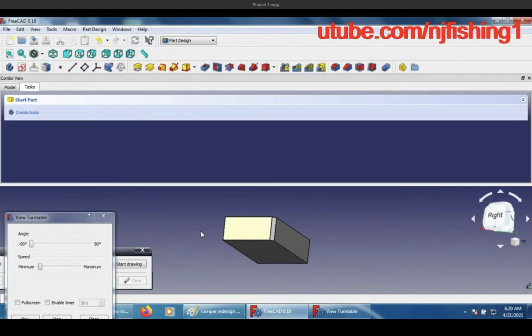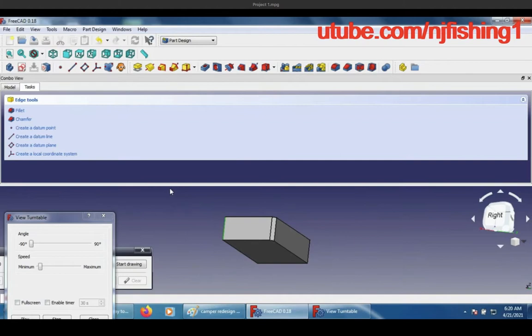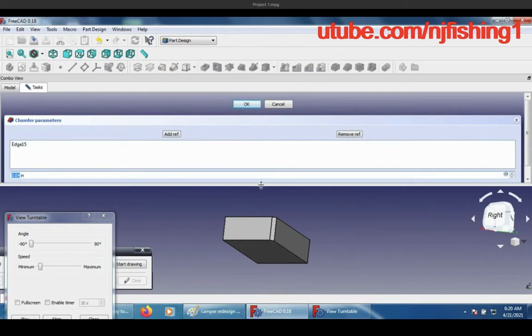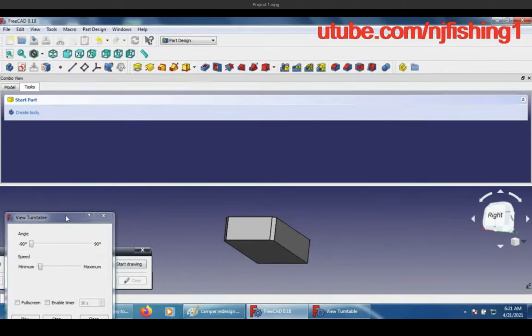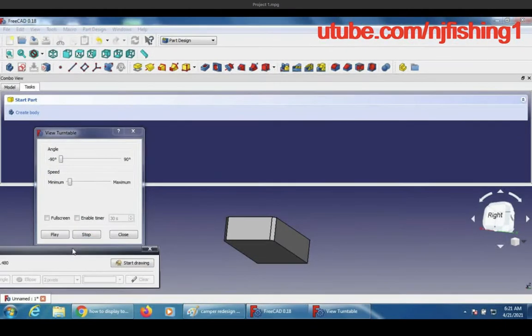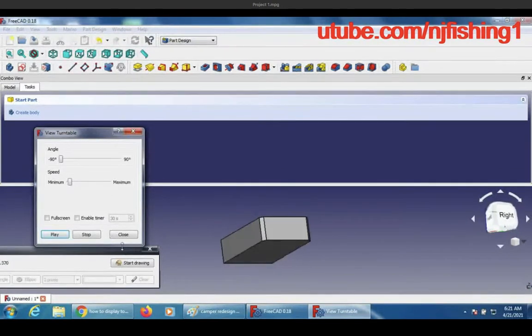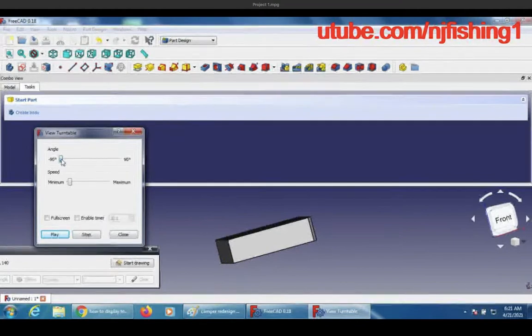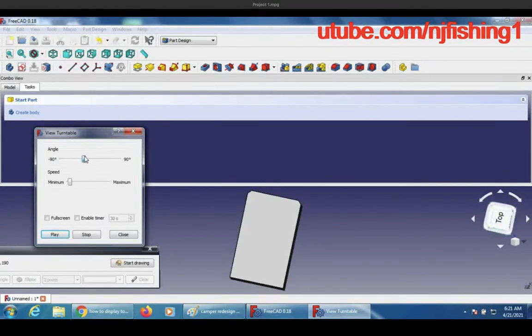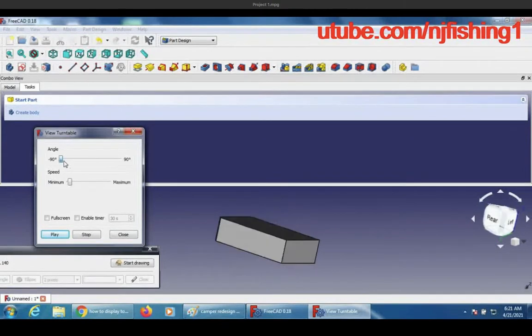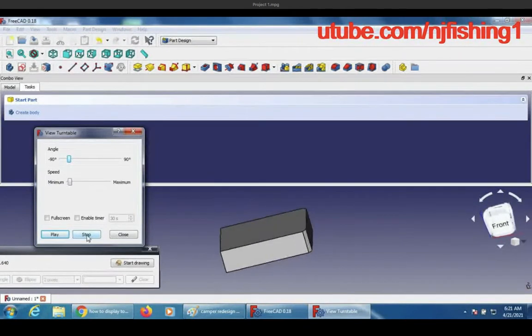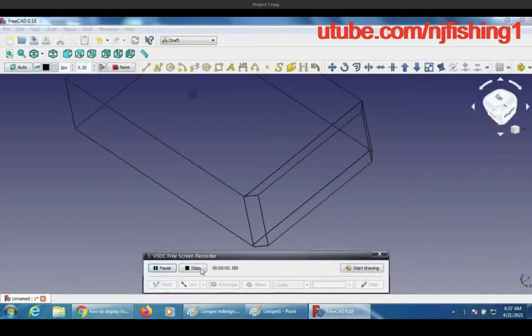First I did 5 inches, and I see it's pretty small, so I'm going to change it. And now here I'm doing another chamfer on the other side. Instead of 0.04 inches, I enter 5 inches. You can see it's pretty small. The point of this is to get better aerodynamics, and the chamfer is a lot easier to do than fillet. Fillet makes rounded sides or corners. This chamfer is still not totally vertical, but has a little bit of an angle to increase that.